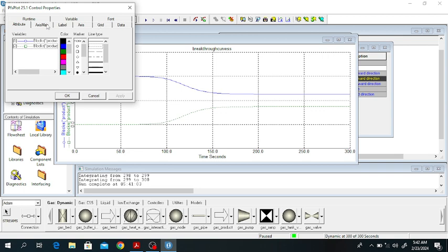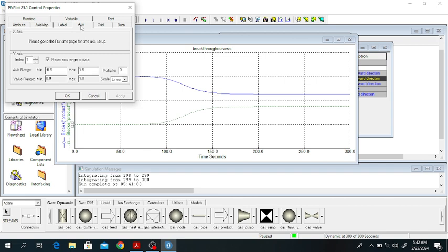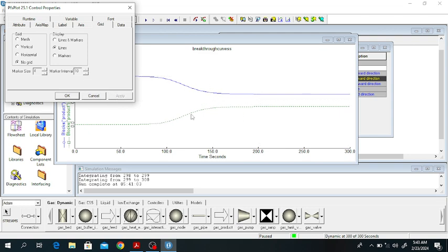Now you can also go to, suppose this is the x-axis, this is the grid mesh, with vertical lines and horizontal lines in mesh form. If you don't need the grid, click on apply, and there is no grid. If you want line and marker, you can change the marker size, like 3, 4. So I'm changing it to 4, and I also want the mesh.